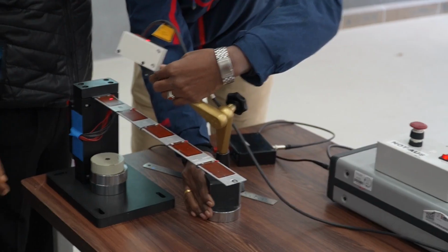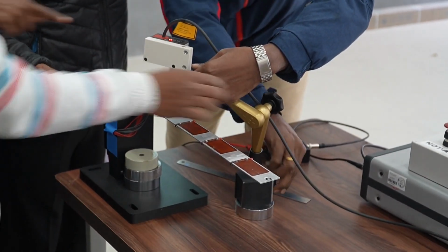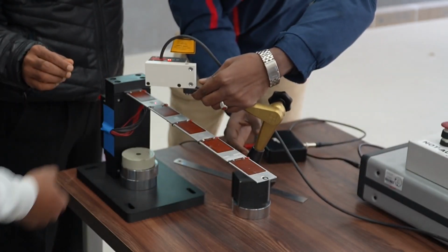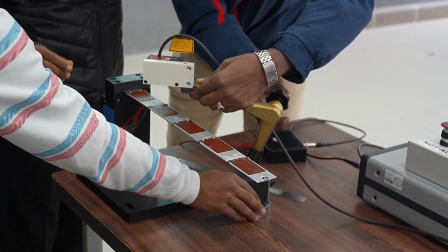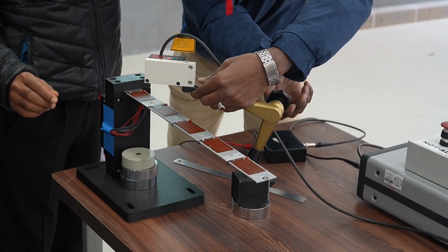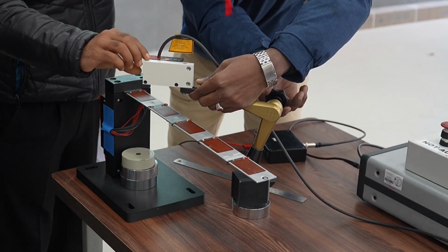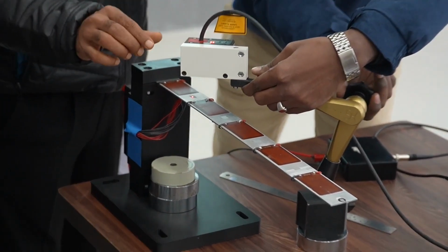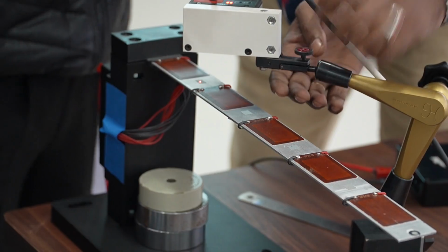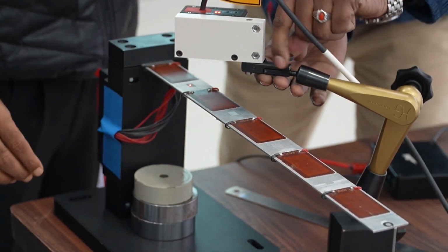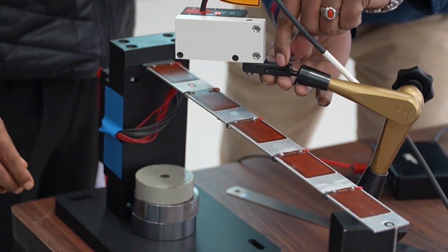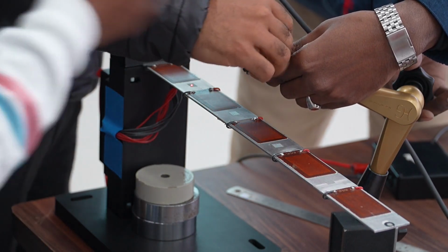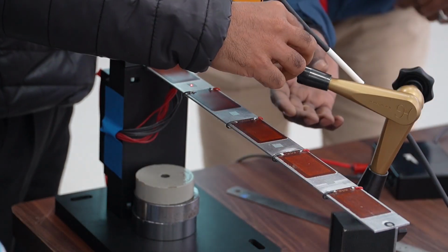And the maximum tip deflection will be whatever the laser shows right now. Okay, and then again we do the difference by putting the tip deflection of the second to third by showing the laser, and then we'll subtract. First we will identify the first mode. Then we will plot the mode shape. No. First you identify first and second eigenfrequency, and then you identify the mode shapes by going into the first eigenfrequency and then into the second for each point, and measure the amplitude.